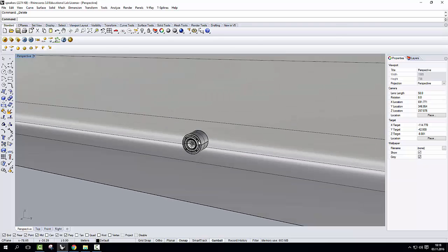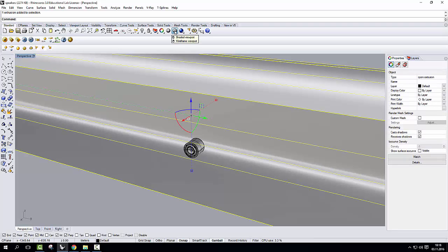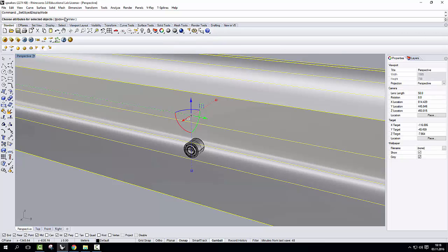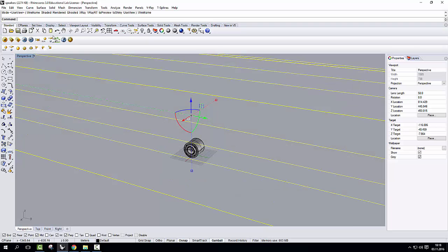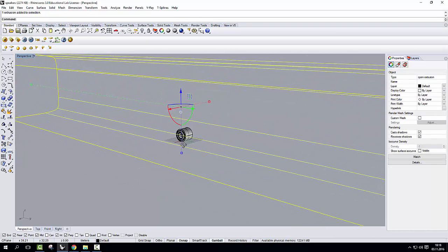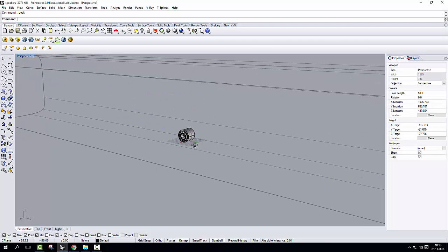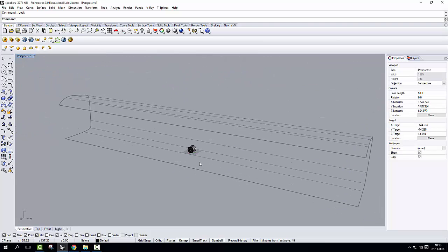And now, just for practicality, I click on this element, click and hold this button. I go down to Set Object Shading Attributes and change the mode to wireframe. Basically, what it does is make it transparent. Okay? And now I can lock it, so I cannot move it anymore, but it's there.